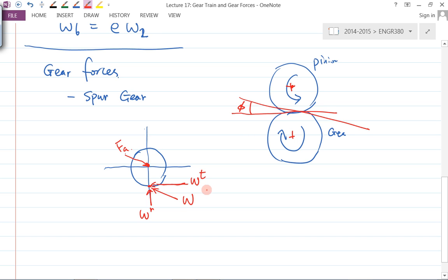Moment, right? Actually here we would call it torque, because you're trying to rotate it. So in order to balance that one, at the location here you need another torque to balance it, which should be the opposite direction. In this case here, it's this direction, TA. Okay. So that's the free body diagram for the pinion.